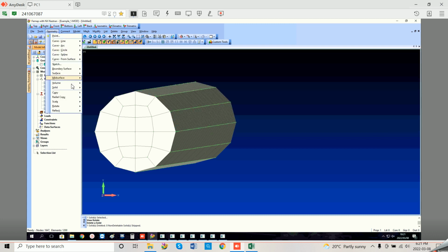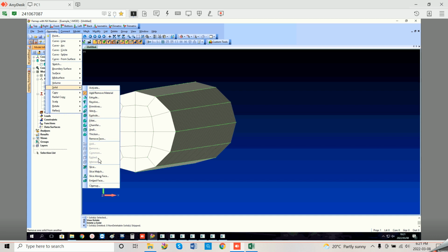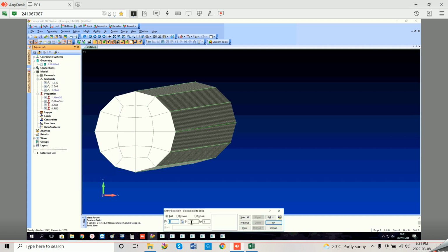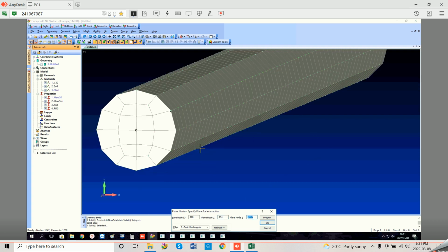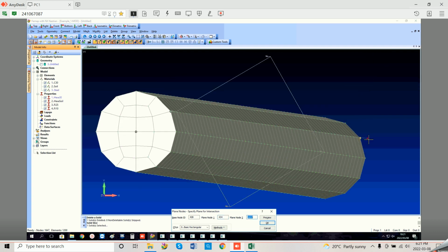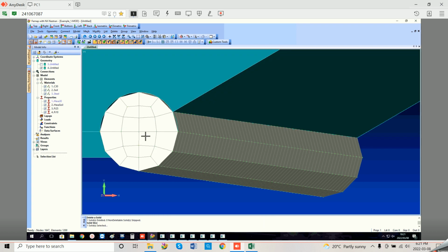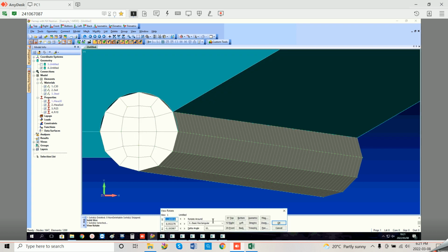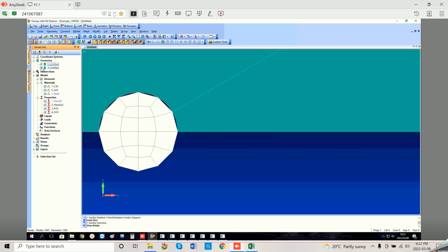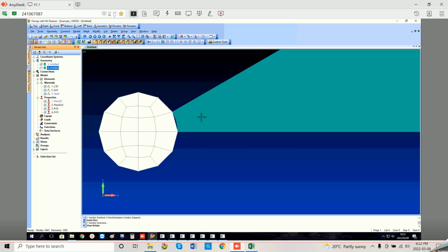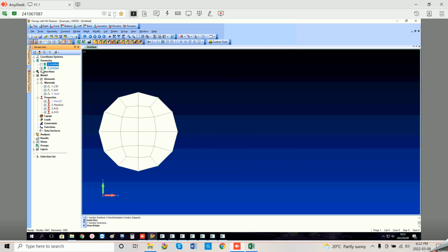So what we're going to do, we're going to go again, geometry, solid, slice, make sure it's number 3, we click OK. And now the node, it's that one, the middle node, and that one. You click OK, and there you can see it has sliced it again. So there's our slice. So that's number 3. Geometry labeled ID number 3.